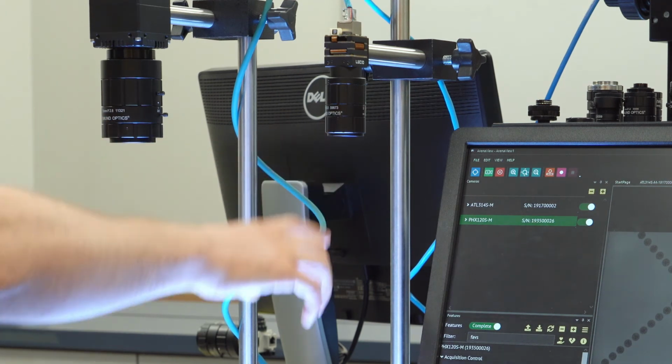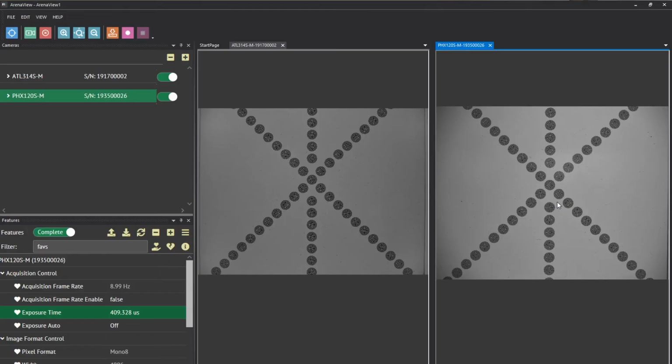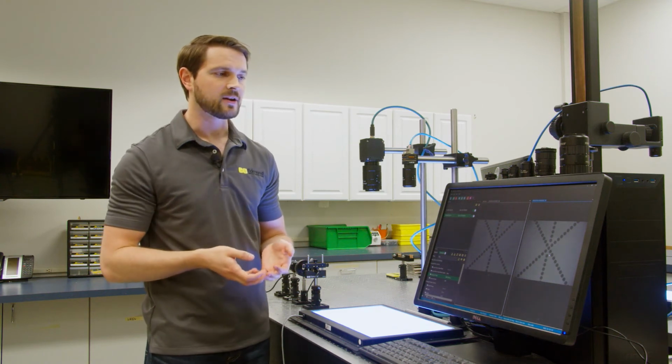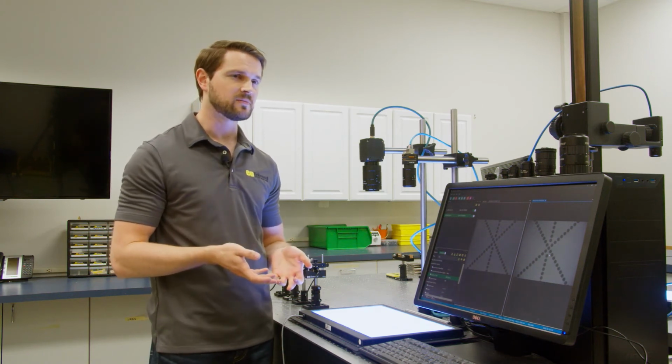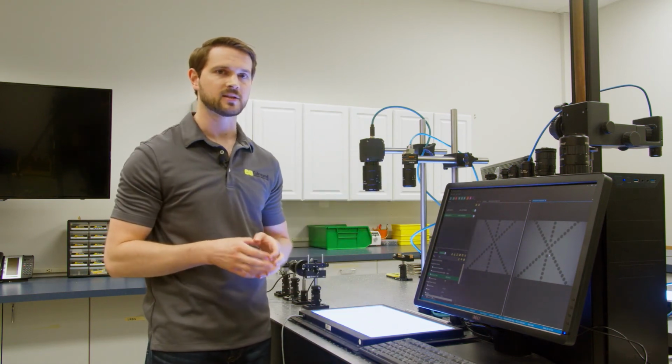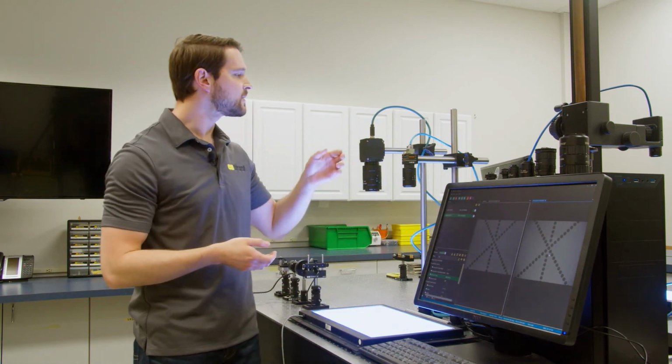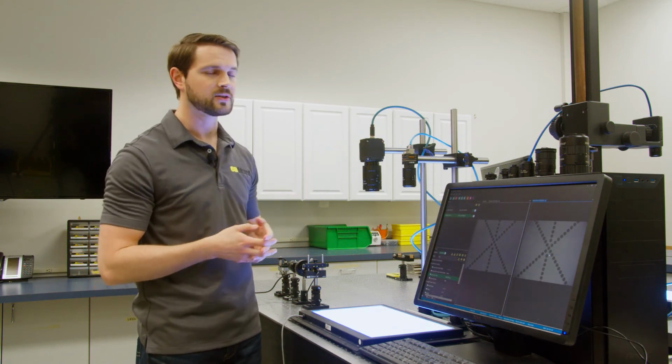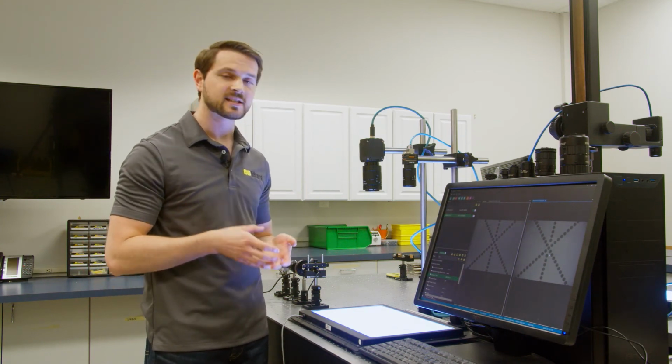And the working distances, you'll notice, are about the same, right? There's maybe a few millimeters different, but they're functionally the same, and we're looking at the same size field. In this particular case, we're looking at this 4-inch, about 100 millimeter horizontal object. These are star targets. I want to take a look at what actually happens now that we have different megapixel counts. Because we have the same field of view but different sensor sizes, our magnifications are actually different. The magnification on the 32 megapixel system is higher.